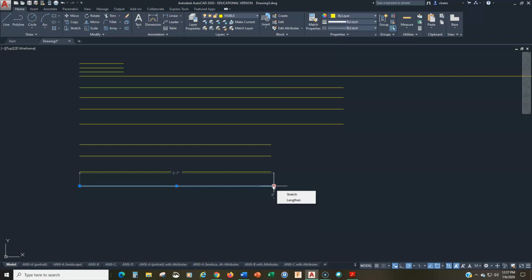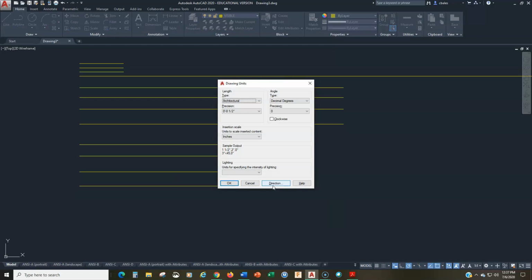All right. Now, as I said, in the architectural drawing that you're going to be creating, there is no dimension less than a 1/2 inch, so you'll never run into this. But if you don't like that, if you want more precision, you're certainly welcome to go back to units and set this at 1/8 of an inch or a 1/16 or whatever you want to. I'm just saying that for our drawing, 1/2 inch is the most precision that we need.